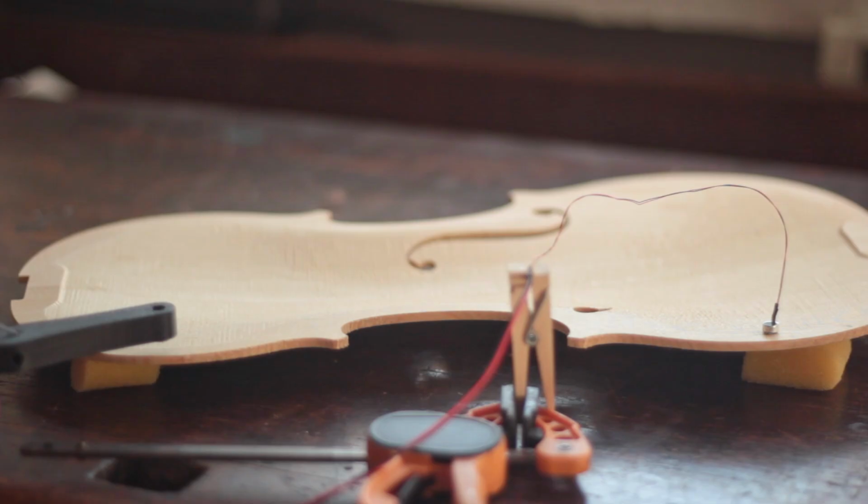The last method for today is the general transfer function. I will show the example of a violin plate. This is a CNC cut top plate. Keep in mind that this is a general method, so it could be used for many other applications. For example, I use it to record the vibration properties of top and back plate blanks. From this, the material parameters can be deduced.